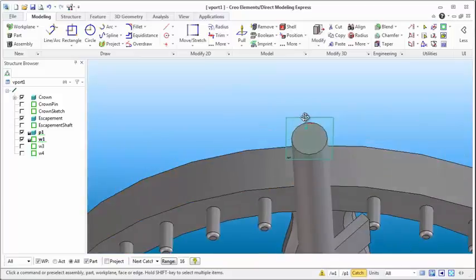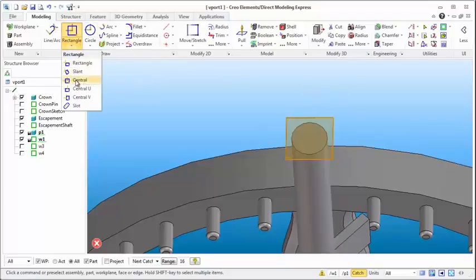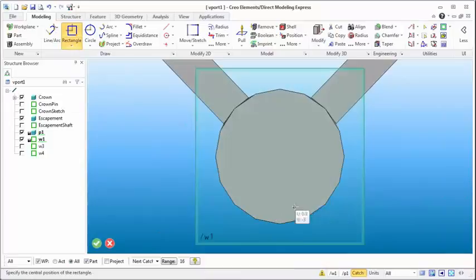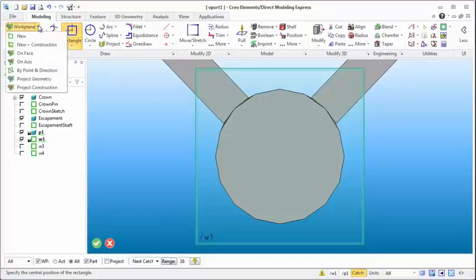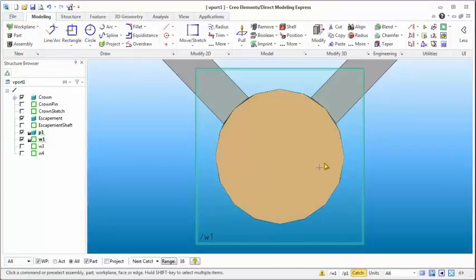So the next thing I want to do here is create a sketch on that plane, and we're going to do a central rectangle, and we'll see if we can snap in on some of the circle. Now the one thing is that circle is at 0, 0, and you'll notice that I can basically come in and mouse over that and get to 0, 0. But if I had created the work plane and I did project geometry, it would have projected that geometry there so that I could have used some of that for snapping to it. I'm not going to be too concerned about that right now, and what I can do here is just start again with the center rectangle